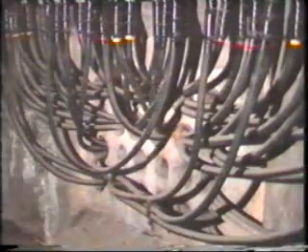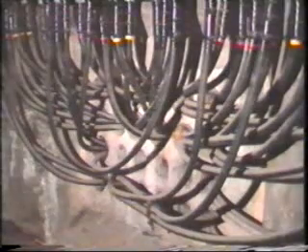This condition is more likely to occur where voltages are 12 kV and higher, and also where the line capacitance is high, for example, with long lines or where cables are used. When you think of all of the variables in the circuits, this subject of ferroresonance is obviously highly complex. But it is essential that we understand the principle, because we shall be meeting this term in future tapes when we discuss specific installations.